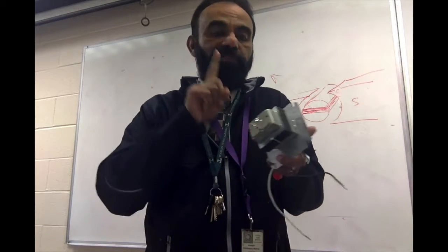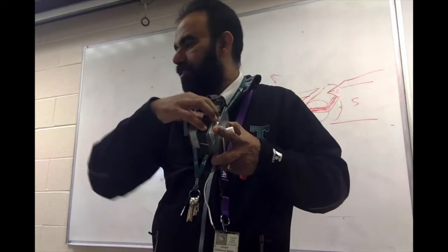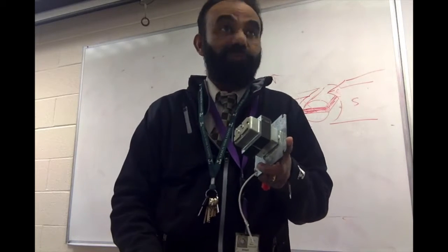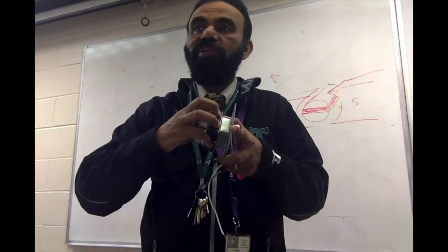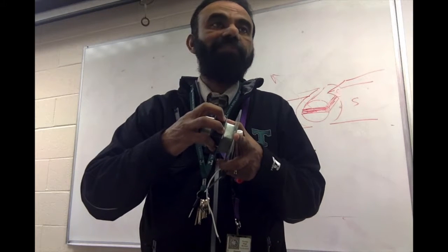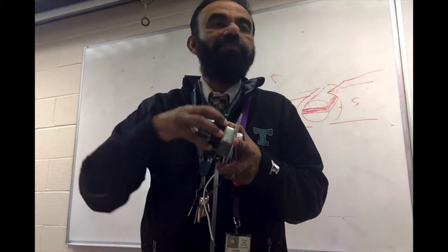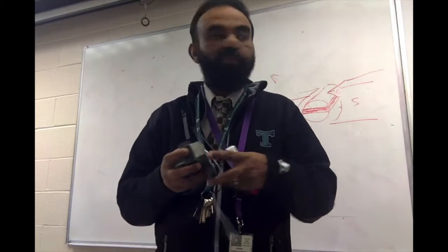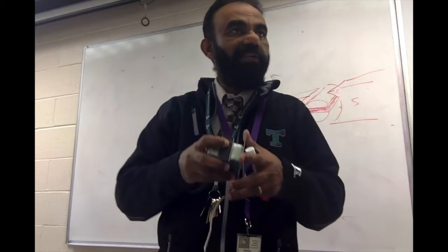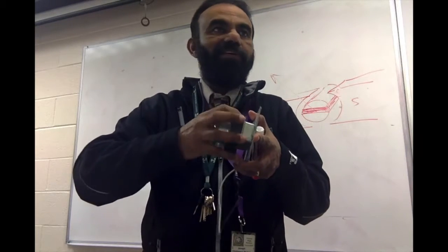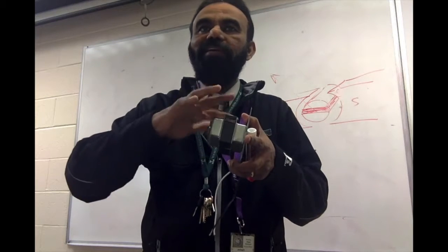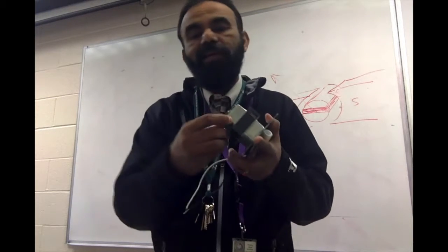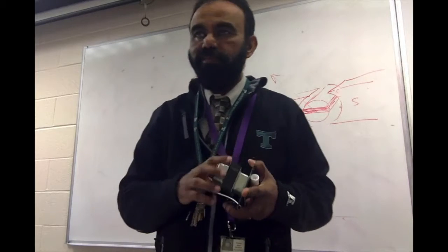Now instead of this laminated core, if I use a solid core and connect it, what will be seen is this thing becomes really, really hot because of the eddy currents. And that will remove the efficiency. So if you're going to take 100 watts from there, out of 100 watts, 95 watts will be gone as eddy current losses here as heat, and only a little bit can be used later.